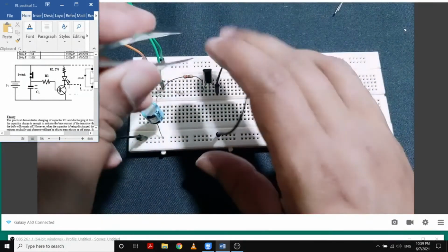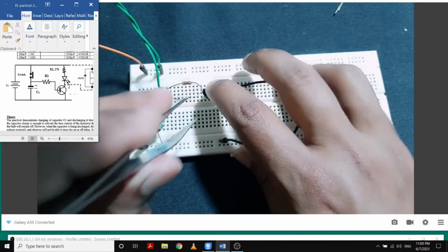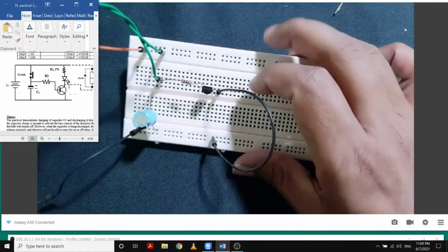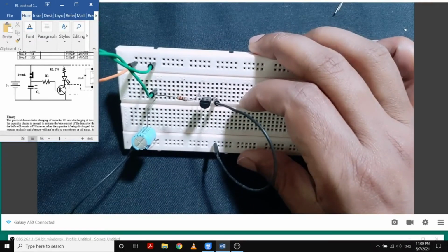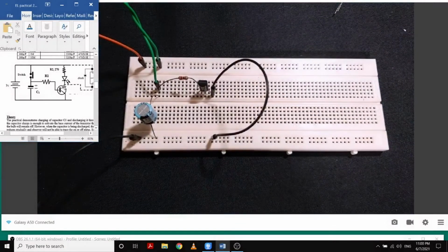I'm going to turn this transistor here so that it will be very visible to you correctly. And then what we need to do is complete the circuit for the collector in this part, with a resistor and LED bulb to the collector, right?